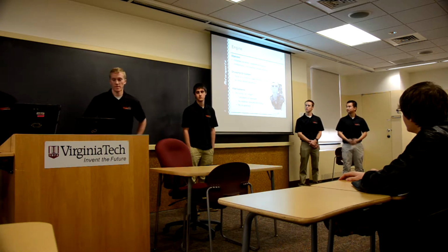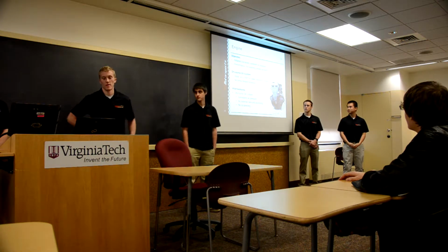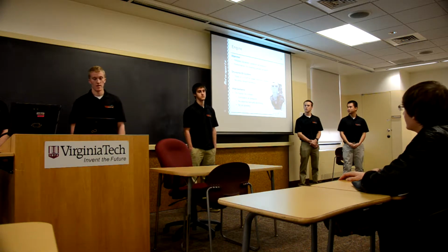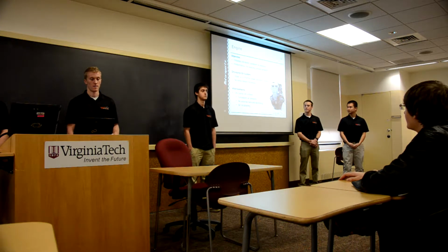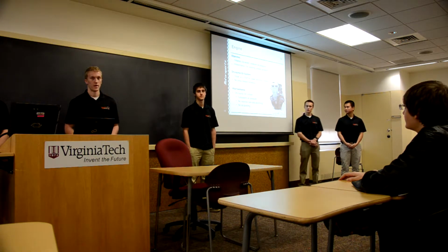For 2014, we're looking into getting a new WR450 engine. The 2007 engines come stock with a fully integrated oil system. It's dry sump, and we plan on running it stock. It's an improvement from previous years where they ran a semi-dry sump. The dry sump has advantages: there's no oil pan, so there's no sloshing, it limits aeration, and you get consistent oil pressure.